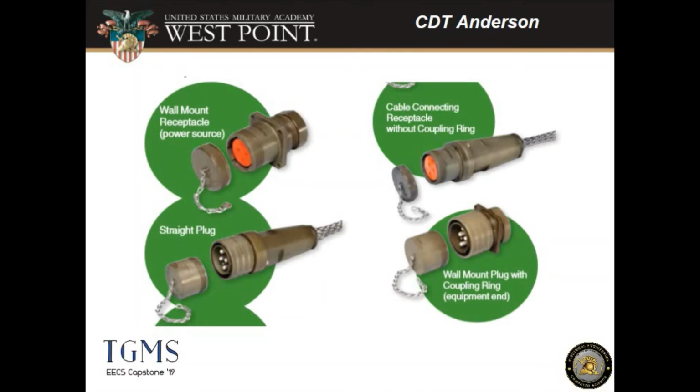The first design aspect we had to choose was whether it was to be wall-mounted or a straight plug. This is a pretty easy design choice because we were dealing with a portable type design, so a straight plug made sense. Next, we had to choose which side would have the male-female connectors. Since the monitoring system connects in series with a generator and a tactical power distribution unit, it would use a male connector to connect to the generator on one side, and then after it passes through the monitoring system, have a female connector at the output to connect to the power distribution system.